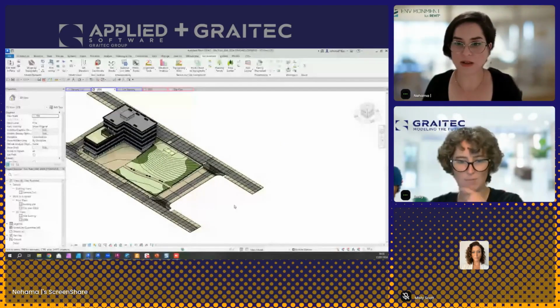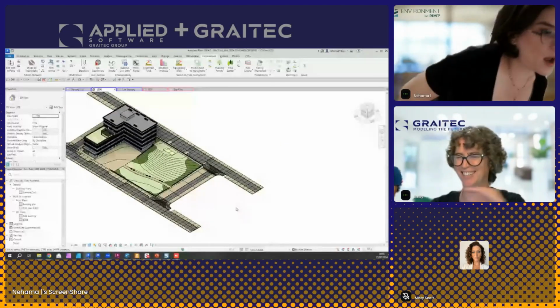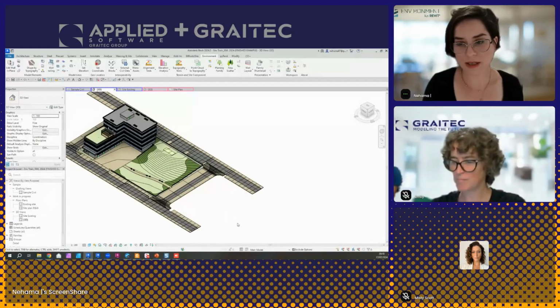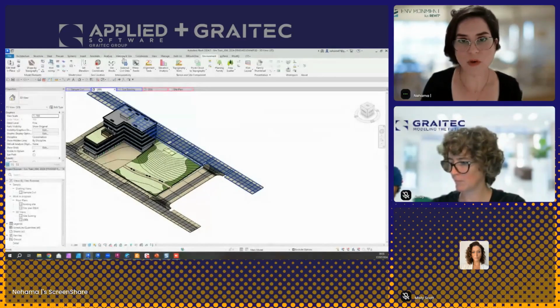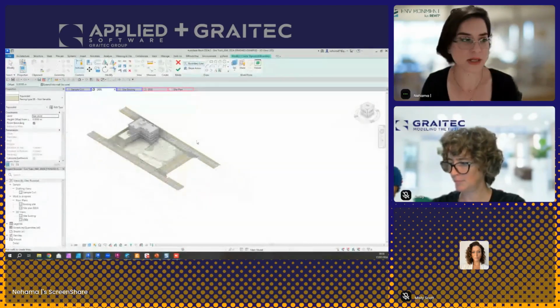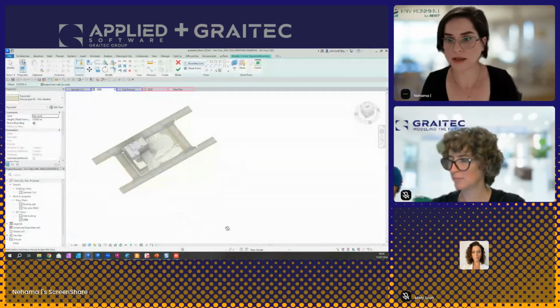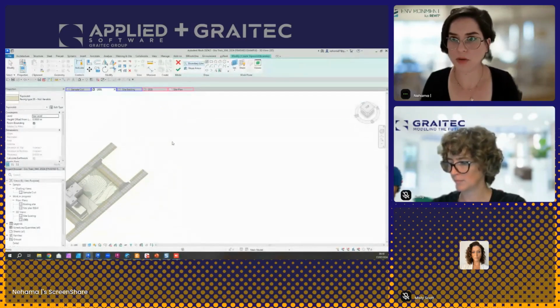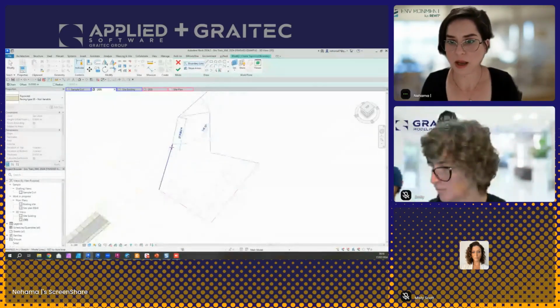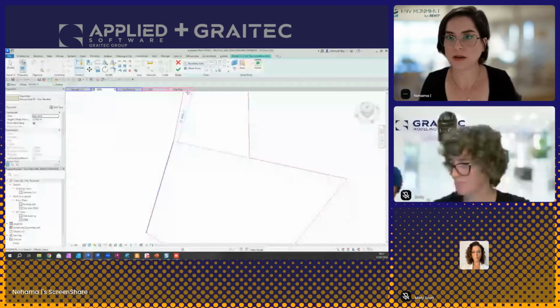All right. So let's take a look at how do I add a reference surface. So basically, if you guys remember, when we're just using meshing and site tools, when we have a topo solid, it's basically like a floor, right? It's composed of a boundary, right? I can create a boundary of some sort, and let's close it.